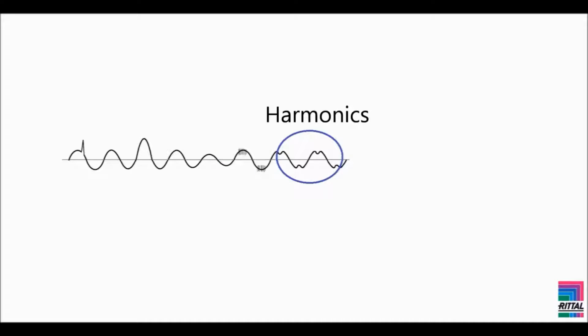Harmonics. Deformation of the sine wave, generally caused by nonlinear loads, which draw current from the mains supply in large peaks. Harmonics can cause a rise in current drawn from connected equipment, resulting in increased temperatures, followed by potential overheating and component failure.